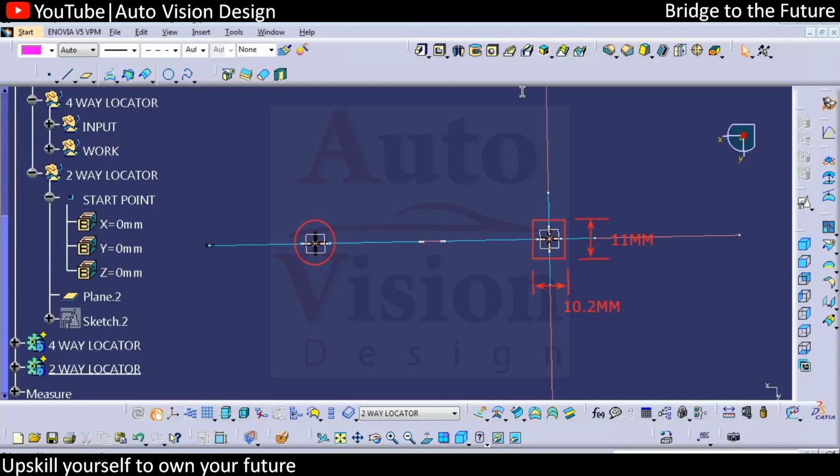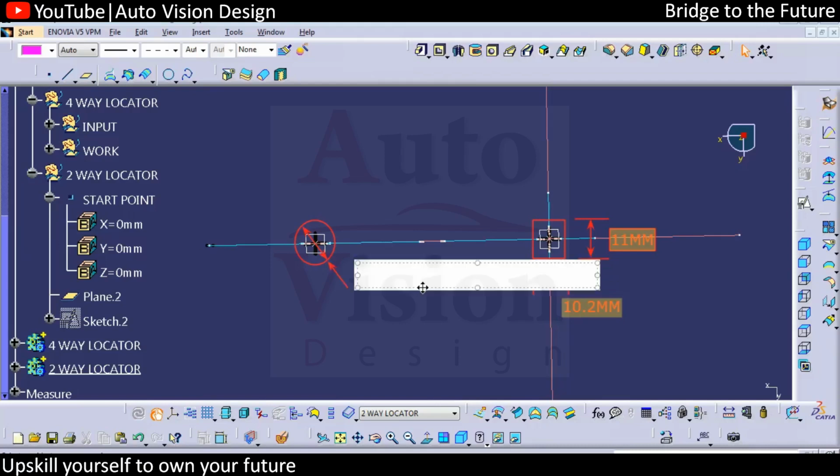Clear? So where is this dimension coming from? Whatever value we have for the slot, that slot value is changing, and here you can find the dia of the circle will be 10 plus 0.1 each side, so that will be 10.2.